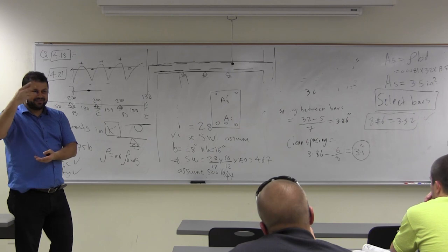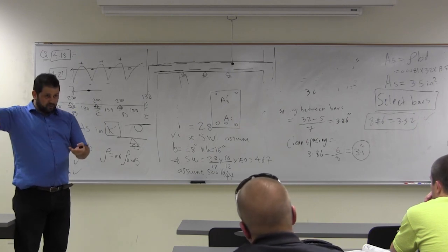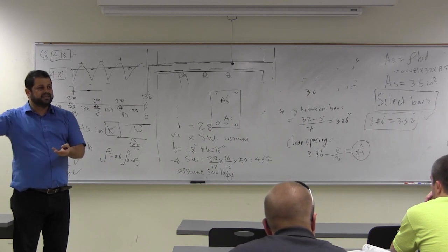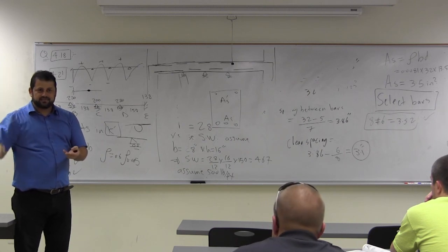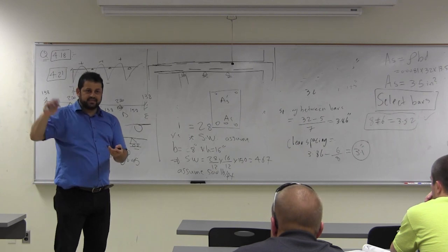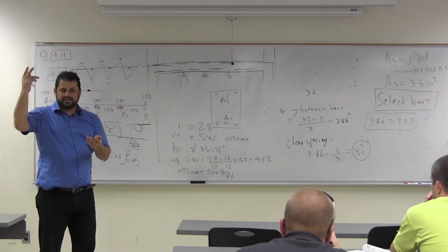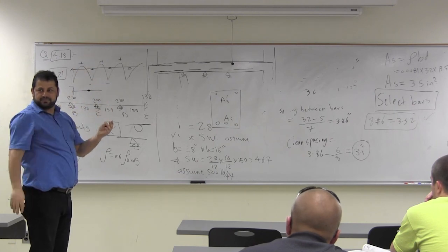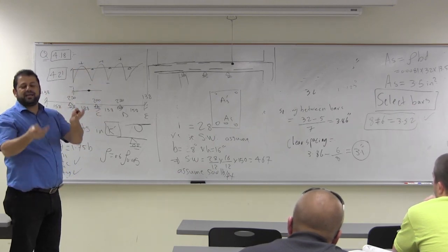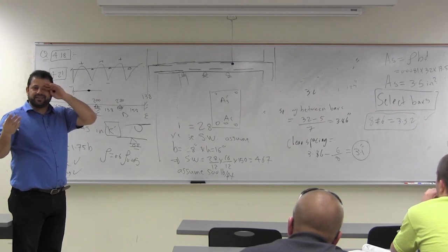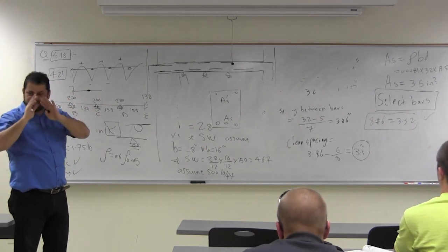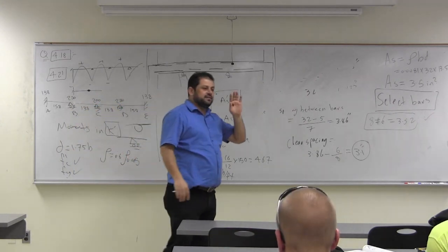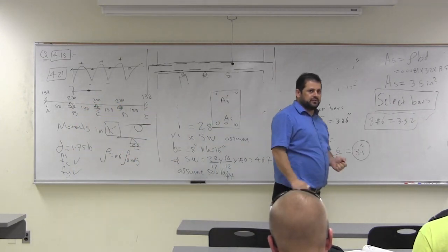In this case, what do we have? Tension, compression from the concrete, compression from the steel. So we'll have T, C, CS, or CS dash. Compression from the steel. So the equation will be T equals C plus CS dash. Then we're going to have the strain in the compression steel. We're going to have to check whether the compression steel yielded or not yielded. That's the only problem. If it yields, so easy. If it doesn't yield, we need to do one more equation.